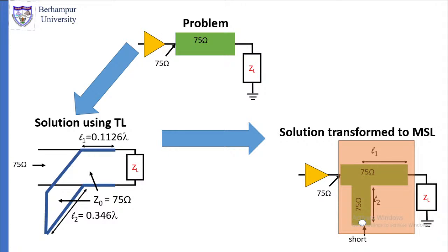There we have drawn a hole on the coaxial cable. From the outer point we will drill a hole, take another coaxial cable, and then the center connector will pass through this hole and be soldered to the center connector of the main line. Then the outer part will be soldered to the outer part of the main line. Now once the frequency changes, this matching will not work.